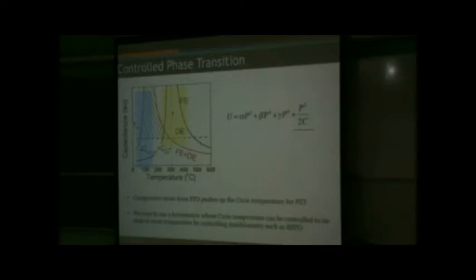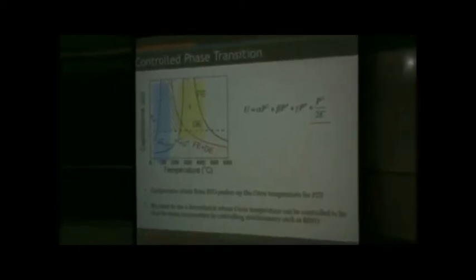So that is a controlled phase transition that we want to do, and this is why the materials problem becomes extremely difficult, because materials do not want to be controlled like this. They will break into domains, they will give all kinds of issues, and all these complex material systems are very difficult to integrate with silicon. We have been working for almost 2 years to make a MOSFET. I keep telling Suman that just last month, after 2 years of work, we have gotten our first 3-terminal results. Forget about good transistors. The integration is so difficult, at least in a university environment.